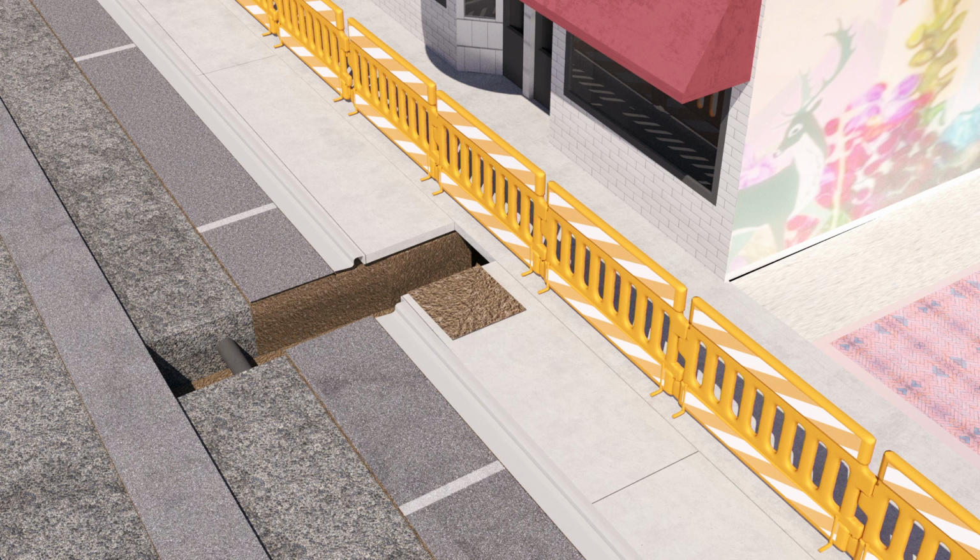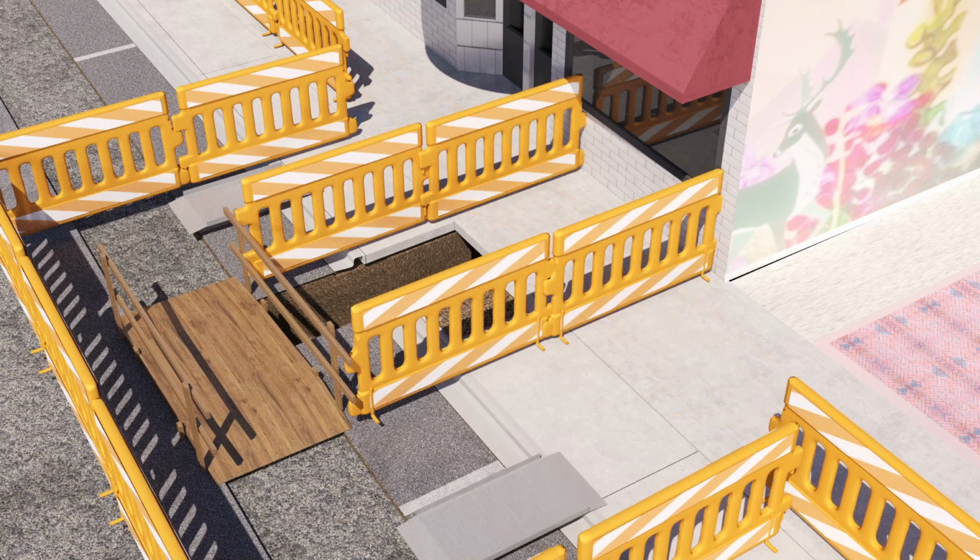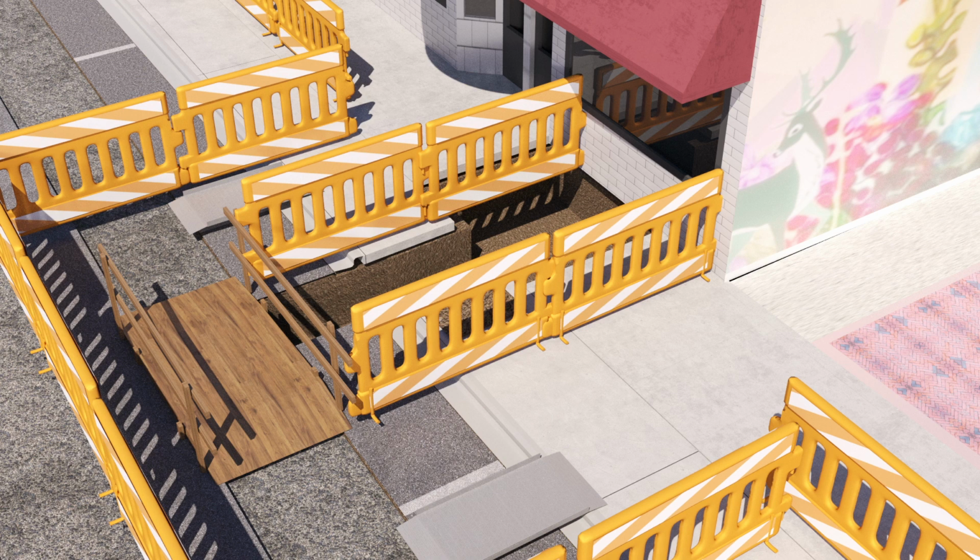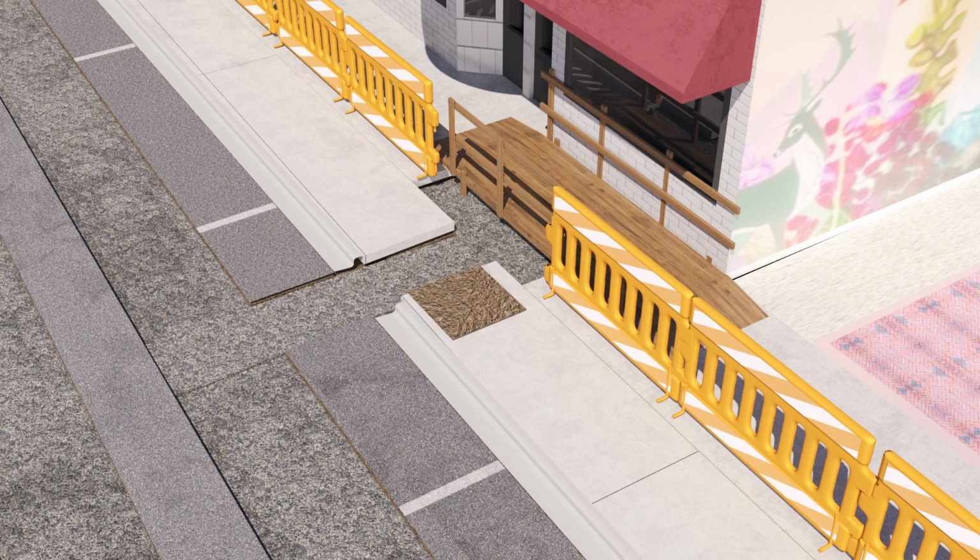Note that in this sequencing, the example sanitary service connection is partially installed as to not interfere with the initial pedestrian path provided. Then in order to complete the connection, the pedestrians are routed into the street, with temporary ramps used to navigate curb lines as well as bridge over the open trench. And then finally, the pedestrians are provided their original routing to allow for the completed sewer connection to be backfilled.